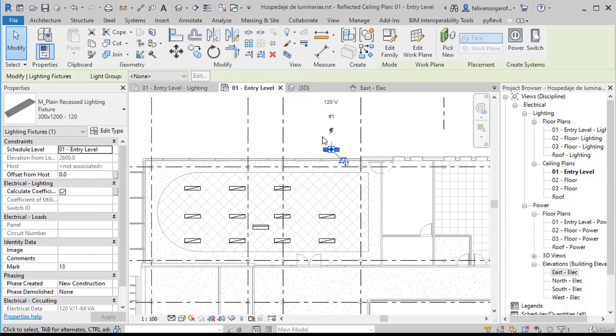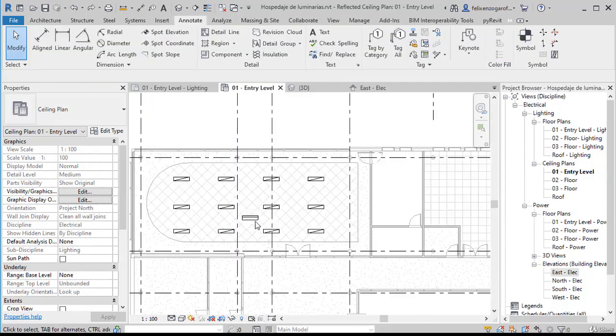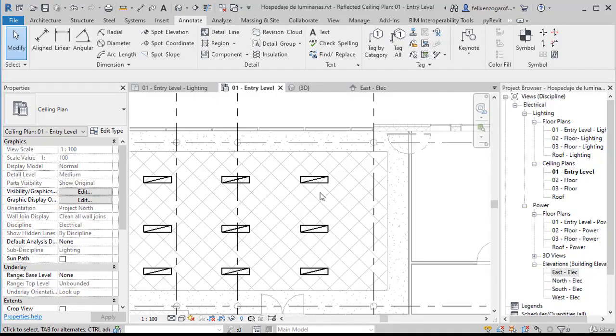Another problem we might have, we will go back and erase this one here. Sometimes in the early stages, the original ceiling that we are using as a reference for aligning the design may be deleted and a new one is created. Simply what the architect does is delete the old and create a new one. That will create a hosting problem for us. What should we do then?